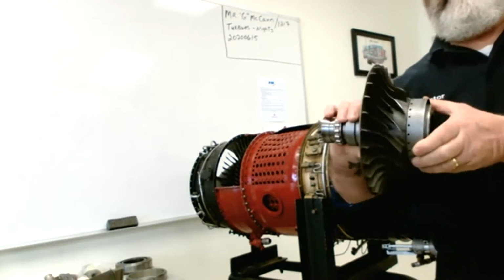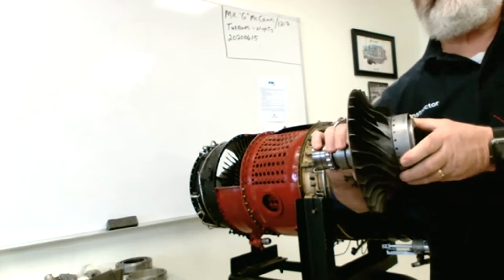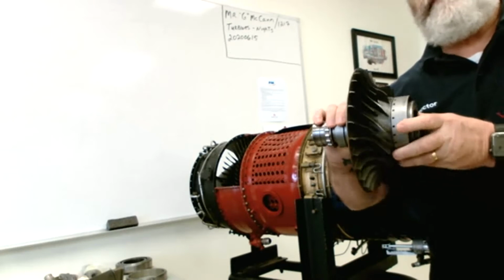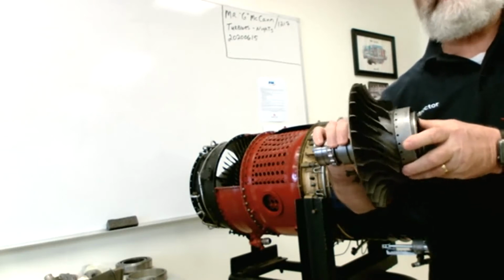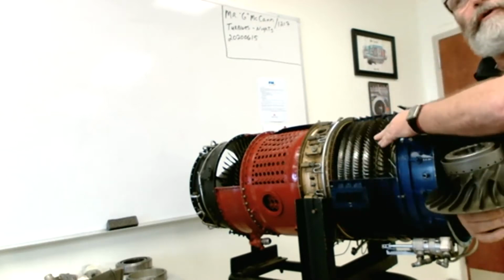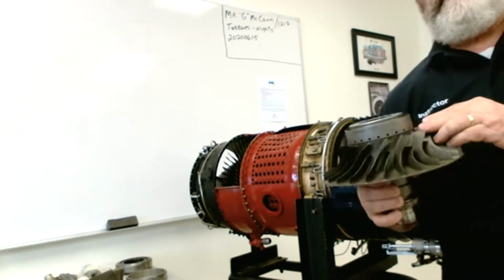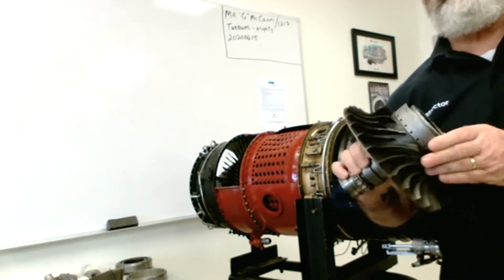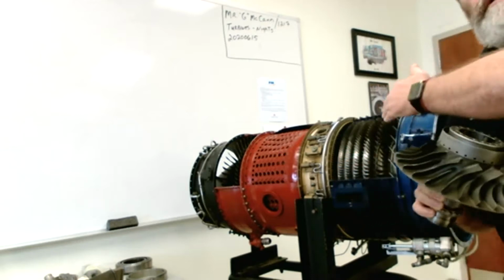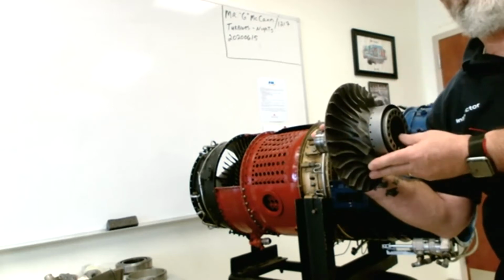However, you're limited to just two impellers or two centrifugal compressors per engine, and after that the disadvantages start to outweigh the advantages, and so that is why the axial compressor is by far the most popular compressor. Now, on turboshaft engines used, say, in helicopters, where the product is not thrust but torque or shaft horsepower, a lot of times they will use axial compressors and then a centrifugal compressor at the last stage.